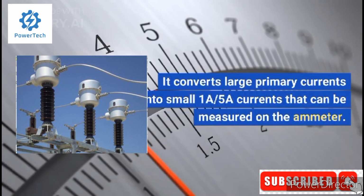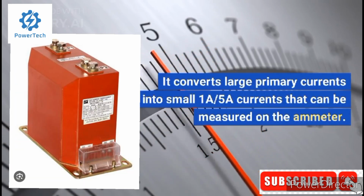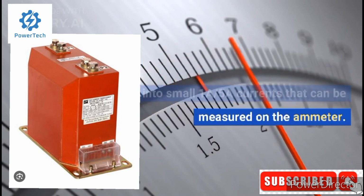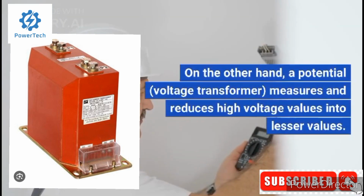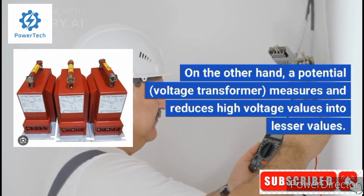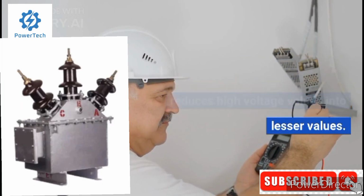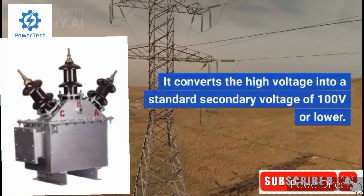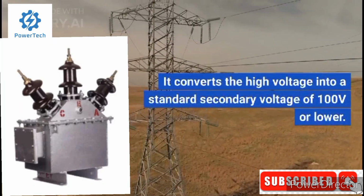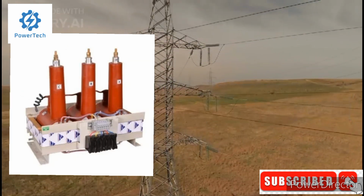It converts large primary currents into small 1A, 5A currents that can be measured on the ammeter. On the other hand, a potential, voltage transformer, measures and reduces high voltage values into lesser values. It converts the high voltage into a standard secondary voltage of 100 volts or lower.